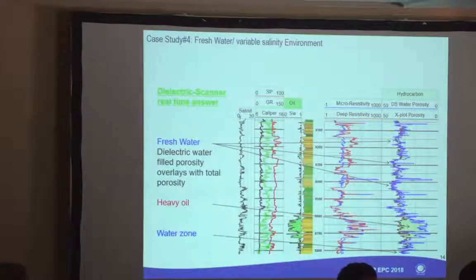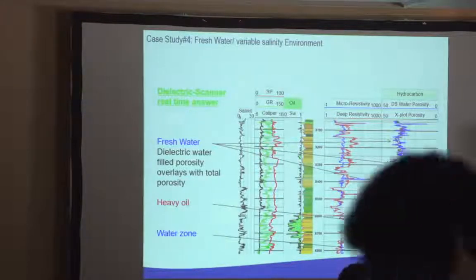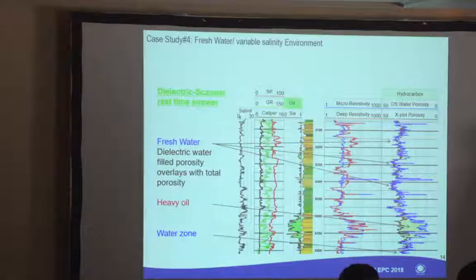So you can use NMR, and this will confirm that you have a heavy oil response. I don't know in your case which logs you rely on to decide to perforate, but I encourage you that for future wells you integrate the maximum number of logs in order to have a better idea. I would strongly suggest the magnetic resonance NMR tool.